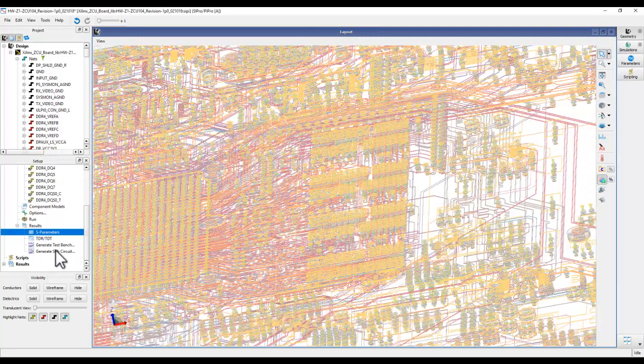And once you're done, you can always create a subcircuit, go back to the ADS schematic, and stitch the whole end-to-end system design, may it be for DDR memories or SerDes kind of channels, finishing the end-to-end simulation and looking at the eye diagram and other quality metrics.